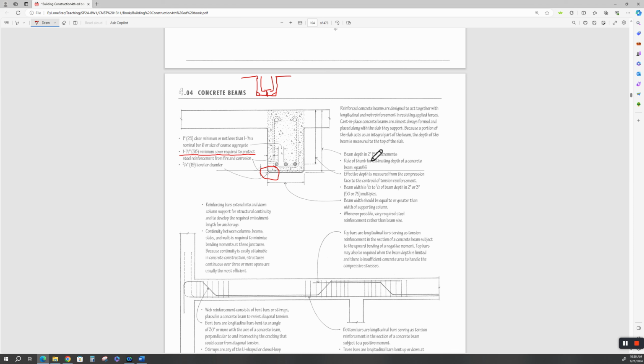And it's in 2-inch increments. Don't do something funky like 1 3/4 increments. Just stay in 2-inch increments. All right. The code for this is the American Concrete Institute, ACI. Long time ago in a galaxy far, far away, I was on a couple of ACI committees as a structural engineer.